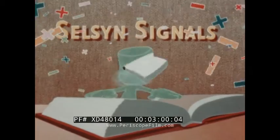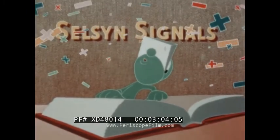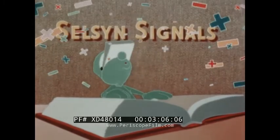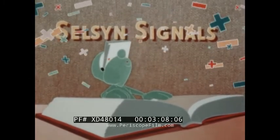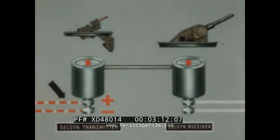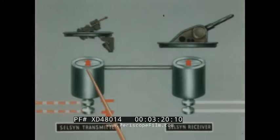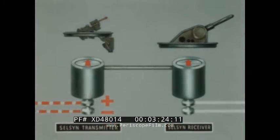The polarity of this alternating voltage is important in considering the direction of travel of the gun. This alternating voltage is applied to the Selsyn transmitter on the sighting station. When the sight and guns are in alignment, as indicated by the arrows, there is no signal voltage from the Selsyn receiver on the turret.